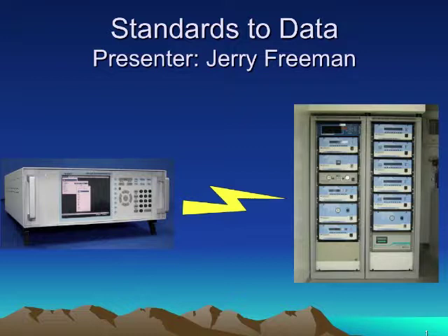I had a question when you talked about the IZS units and after you do the O3 Gen Cal. Yes. And then you average your next 3 automated sequences it runs. Yes. And then, because we haven't got a place where we report percentage deviation from what the standard was to what the next 3 IZS points were. Because I know typically the IZS, your zeros won't come in the same, and you do have a 1 or 2% difference between your standard and the IZS internal cal, even after you've done the Gen Cal and the lamp adjust and all of that. Right.